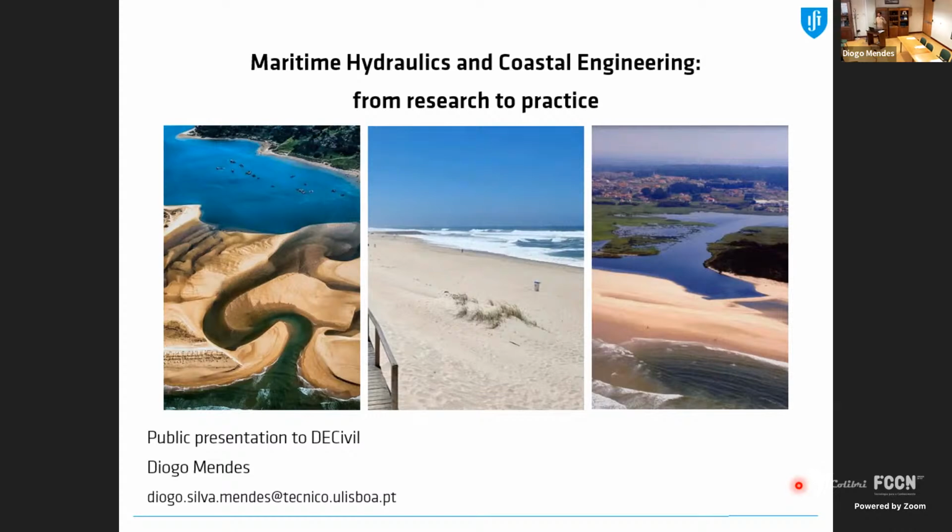You indicate initial tendencies, but imagine that you want to use morphodynamic models to design these solutions. They will just help a bit in the final decision. Unless highly calibrated and verified, you will not use the end result of this model to take the final decision. These kinds of models will just give you an idea of, for example, the longevity of the beach nourishment: 1 year, 2 years, 5, 10.